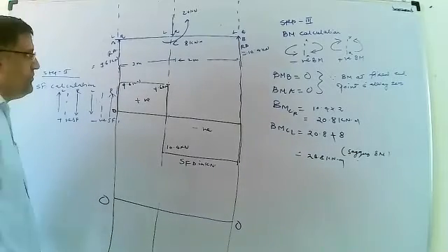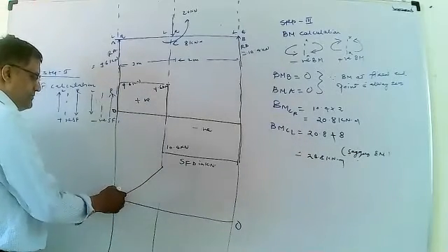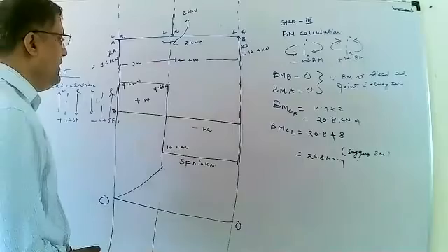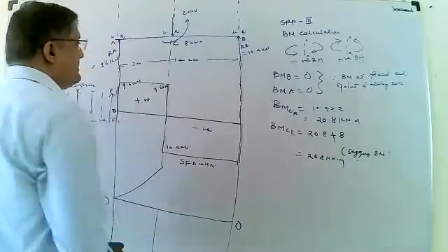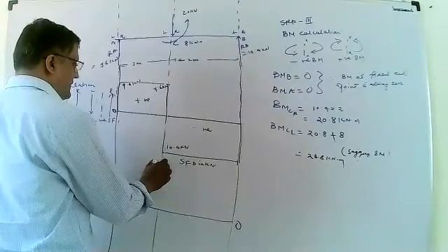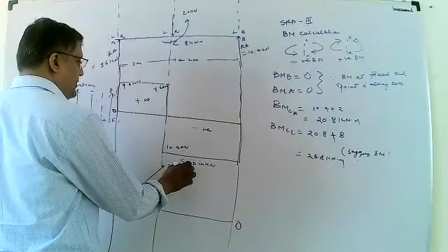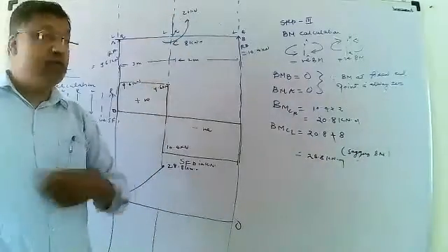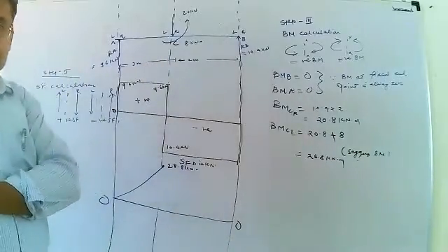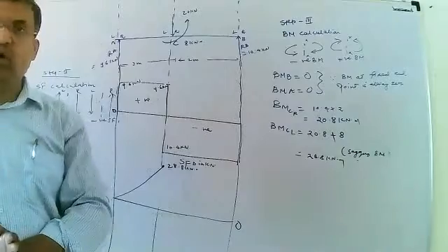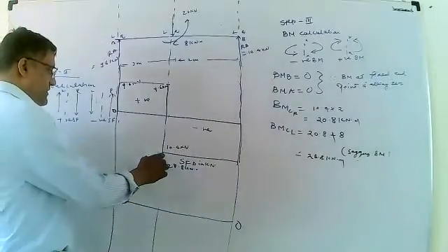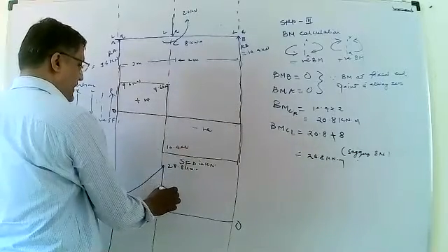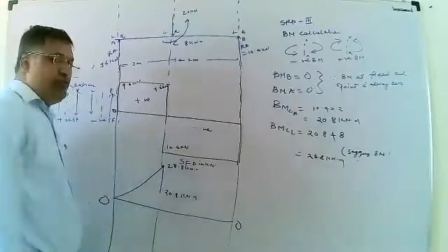Then no load means inclined straight line. Okay. Then bending moment at the left side, that value at the left side is 28.8 kilonewton meter. Then according to the couple moment, 8 kilonewton meter, that is anti-clockwise. Anti-clockwise means it drops, it goes downward. The right side is 20.8 kilonewton meter.